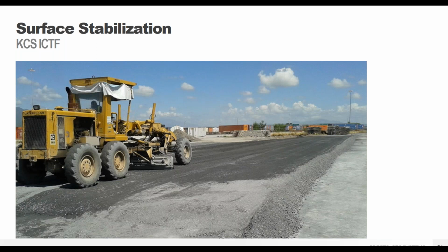And so here you can see the final wear surface being finished to provide that solid surface to support the load. So after placement of that 4-inch wear surface, the railroad decided to add an asphalt tack coat as a surface stabilizer. So while the GeoWeb panels themselves help prevent movement of shifting of the aggregate, for extra peace of mind, you can add something like this tack coat or even a low strength cement grout over the surface, and then there's going to be absolutely no movement.